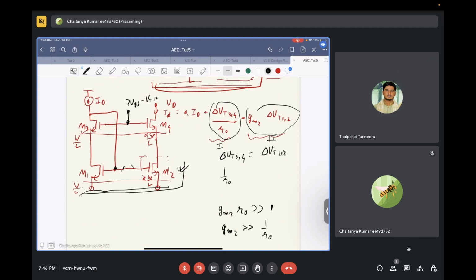For example, you break the node at some particular high impedance point, and say that if this value tries to go up, then this value tries to go down because this is common source. Now you can basically take the circuits from Razavi and check for negative feedback in those circuits.